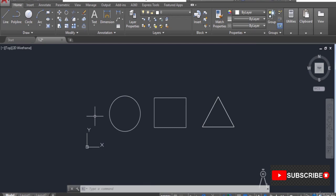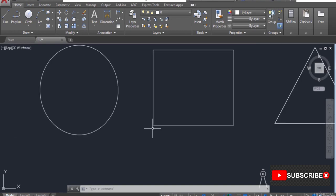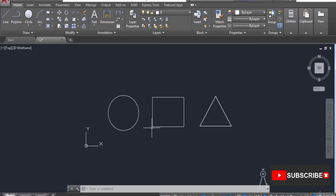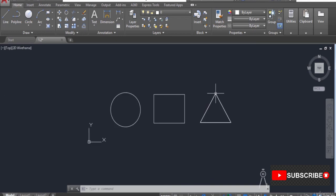Now in order to zoom in and zoom out from the drawing, you simply need to rotate the mouse wheel. So here we have these 3 objects. Let's say that we want to zoom into the lower left of this rectangle. Simply bring your cursor there and rotate the mouse wheel. It will zoom in, and when you rotate it in the opposite direction, it will zoom out. The center of zoom will be the point where you put your cursor. So if I move my cursor to the top of this triangle, it will take this point as the center of zoom, and we can zoom in and zoom out like this.